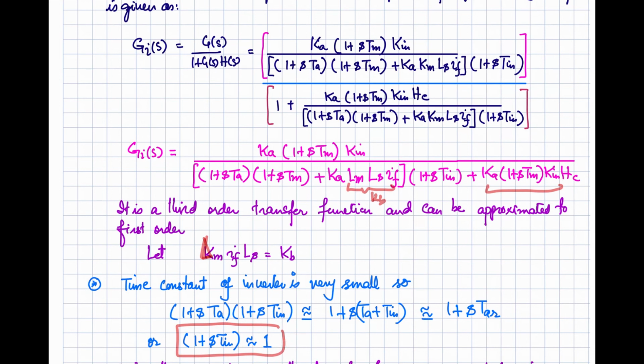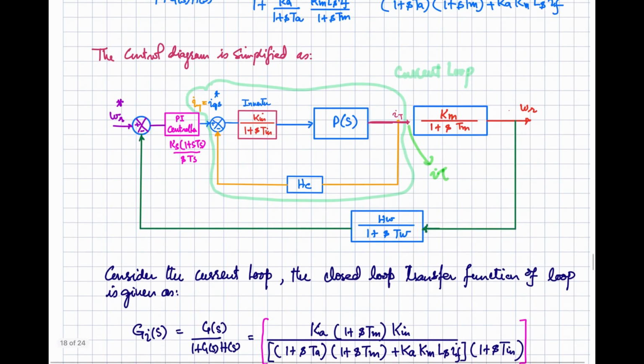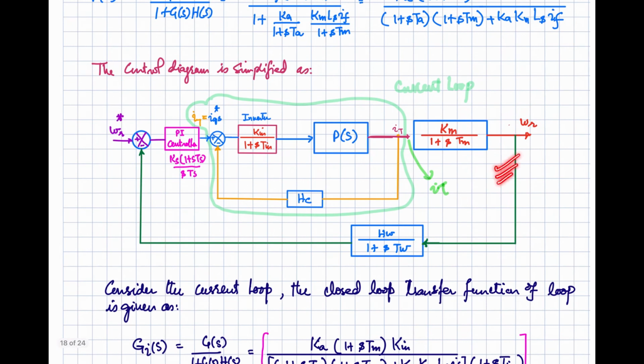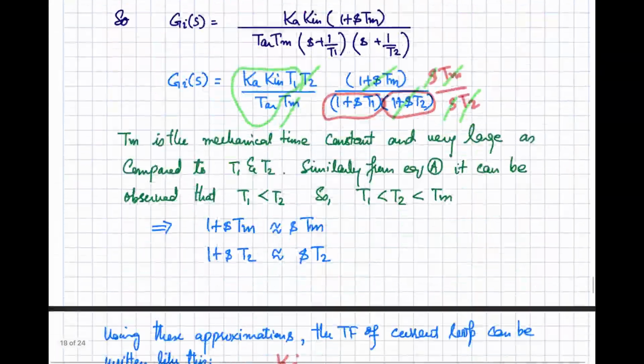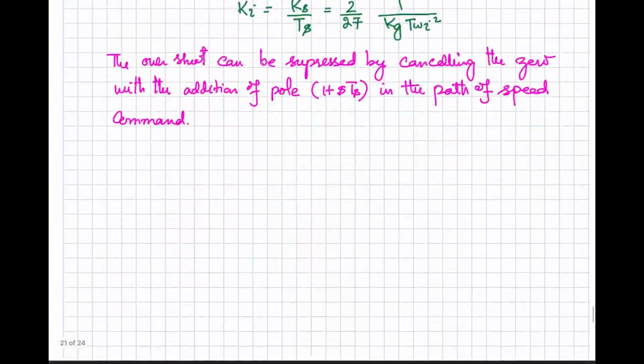So you can do the approximated calculation, and you can have the exact one. You can use MATLAB to simplify this control loop diagram, right? And you can have the exact response, and you can have the approximated response. So the calculations are made over here in this example.